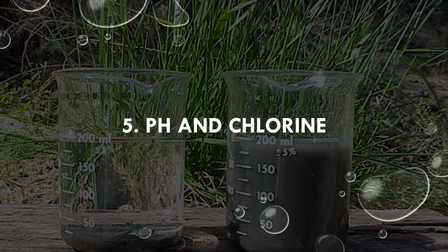So the last application that I wanted to go over is probably the least known in terms of what we do with anionic PAM. If you remember from the first or second presentation in this series, we talked about some of the benefits of anionic PAM for passive treatment. And one of those is that it works in a really wide range of pH, and it does not change pH. And so this application that we're talking about, decreasing pH with anionic PAM, might sound contrary to that.